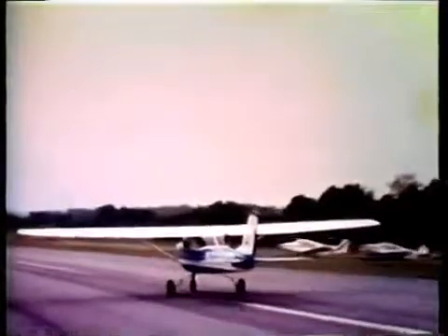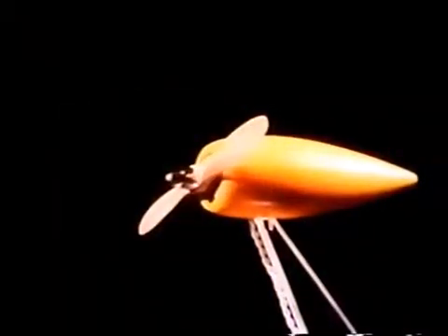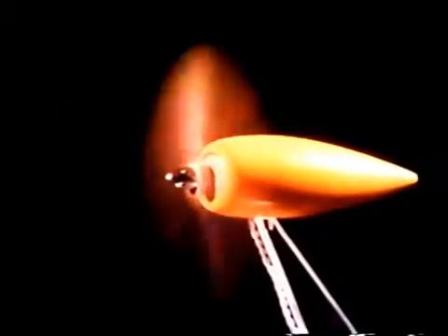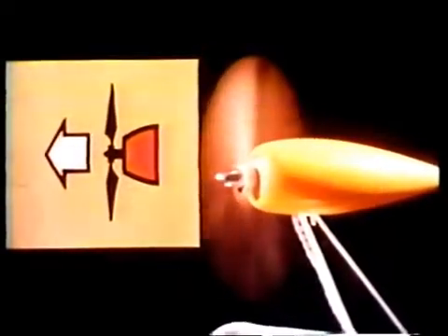First, we need a force to make the plane go forward and create the relative wind. This is called thrust. Since thrust is another of the major aerodynamic forces, we'll tag it with a symbol representing a propeller and an arrow. Thrust is generated by an engine which exerts the force to move the aircraft forward. Aerodynamically, the airfoils of the propeller blades form lift or low pressure in front of the blades, pulling the propeller forward. But what about thrust in the case of jets?